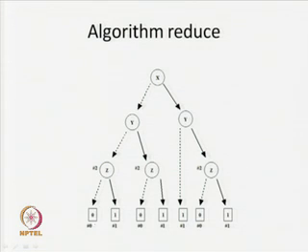because they have the same sub-BDD for 0 and 1. Similarly, when I come to this node labeled z, again we find that they have two different nodes 0 and 1, so it should get a different label. But if I consider these nodes, the behavior is the same, so it is going to get this particular label too. So, first we label the terminal nodes, then we come one level up. Since I have 3 variables, in total we have 4 levels: 3 levels of non-terminal nodes for 3 variables and 1 level of terminal nodes.